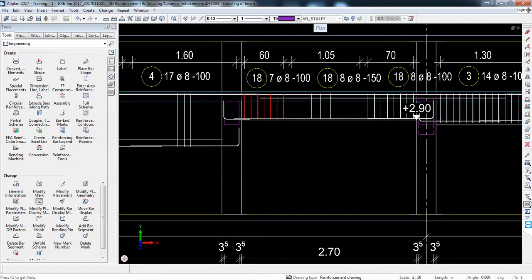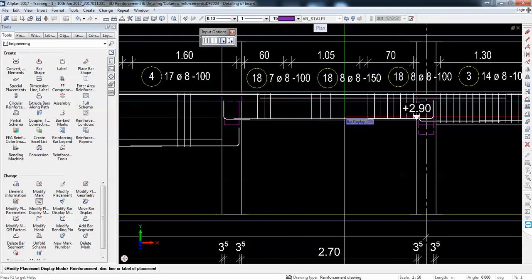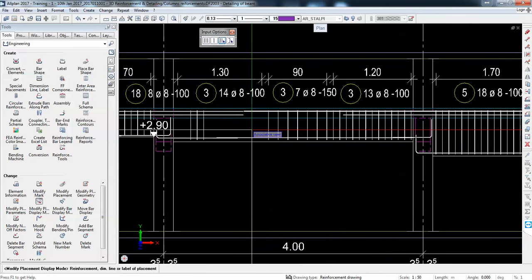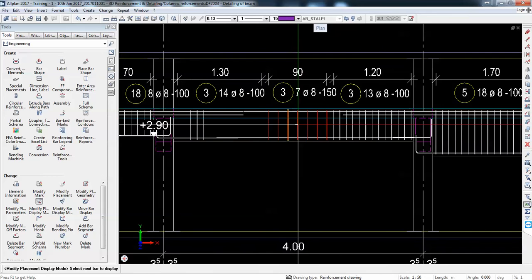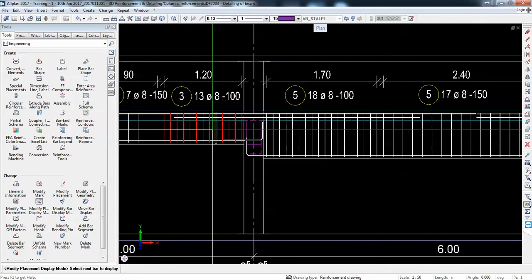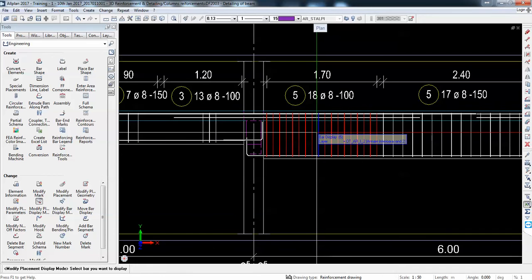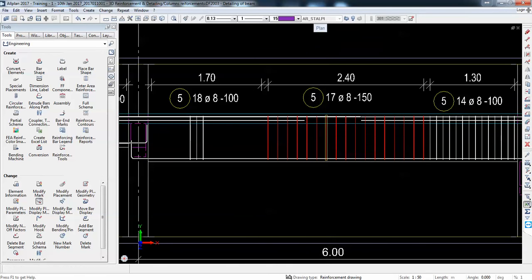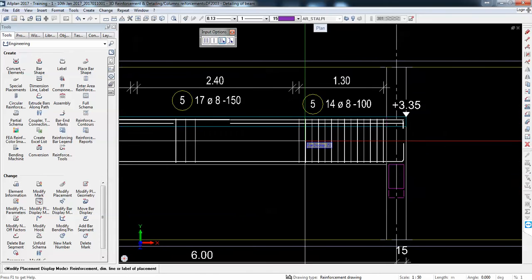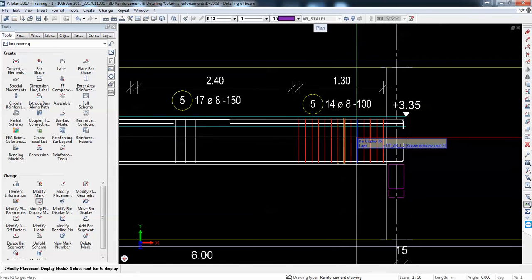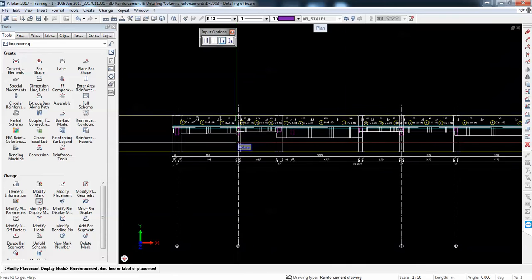So basically, how you'll need to work in Allplan to be efficient, you need to divide your work per operation. So if I want to do placings, I place everything I need. If I need to hide bars, I activate the function and start hiding the stirrups I don't need, so I don't have to look for the function. This is something to remember. In Allplan, once we launch a function, it remains active, and until we hit escape, it will work without reactivating it.